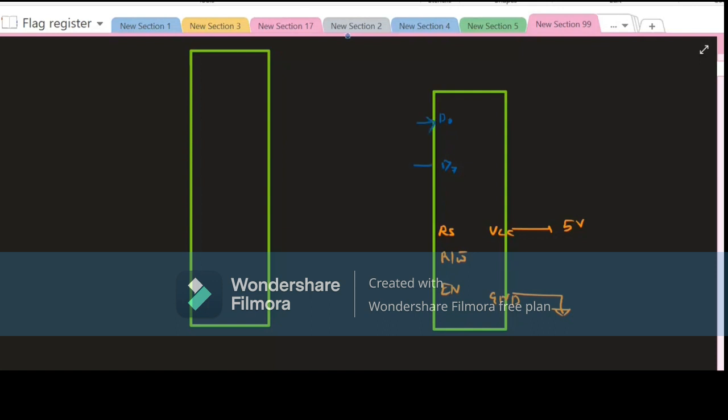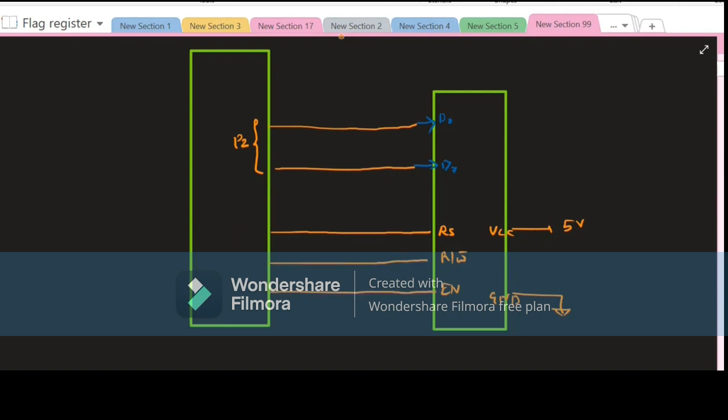So this pin will be connected to port number 0. These pins are basically connected to the microcontroller with the port number. This is port number 2. Now this is connected to some bit of port number 1, some bit of port number 2. We can choose anything. For example, you can choose port number 1 bit 7, port number 1 bit 6, port number 1 bit 5, and so on. And then the rest of this, between port number 0 to port number 1 to 4, you can select